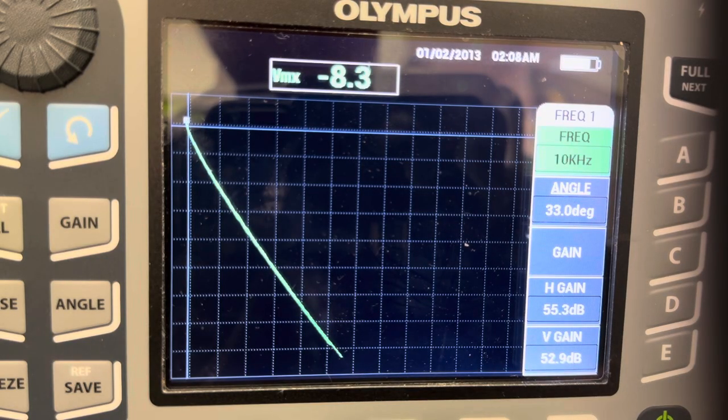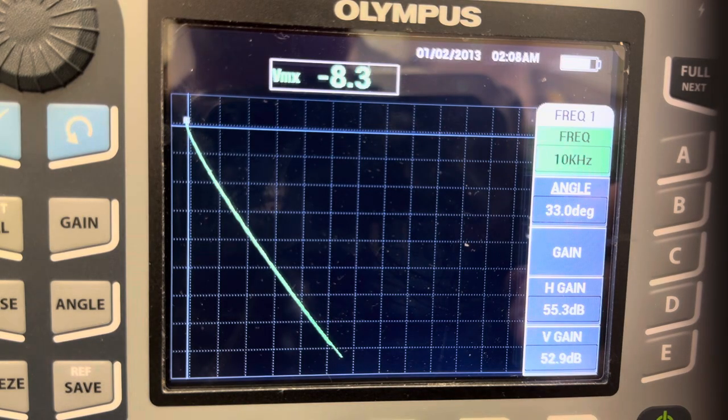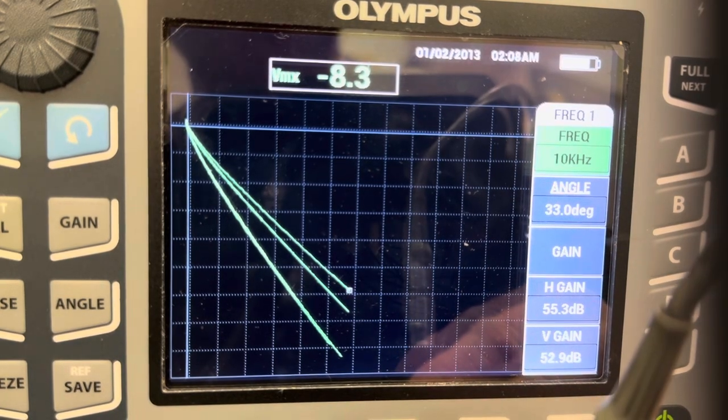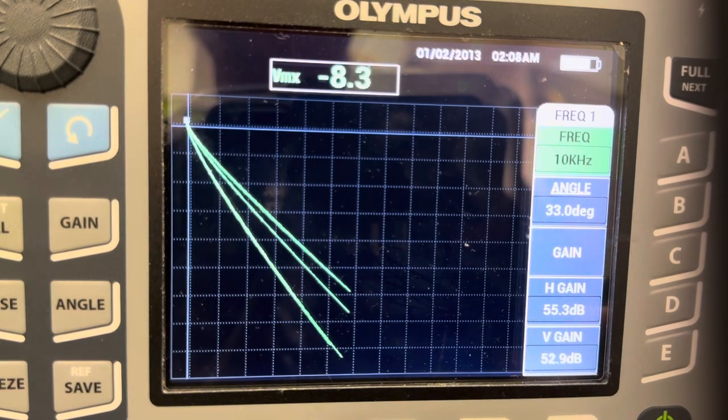Shucks. All right, well, let's try to separate copper from, how about pure aluminum? That's somewhat close, I guess. Those are two distinctly different impedance points. There's a different type of aluminum. So clearly, I can tell the difference between the lower conductivity materials and the higher conductivity materials when I use a low frequency.